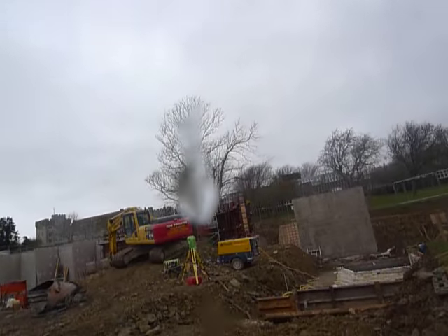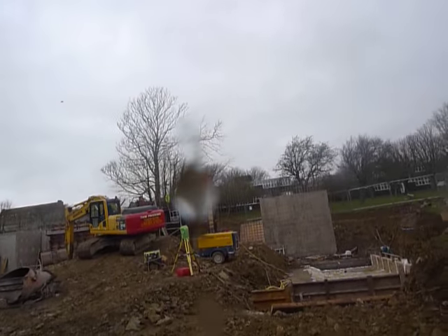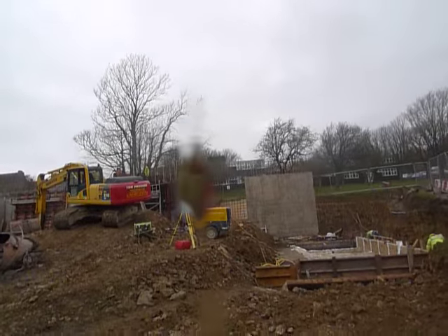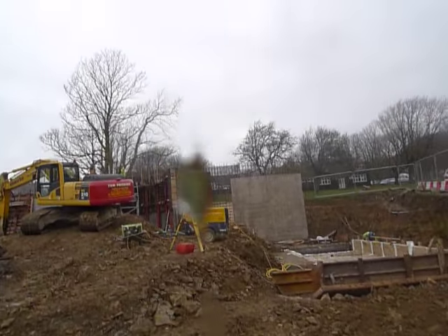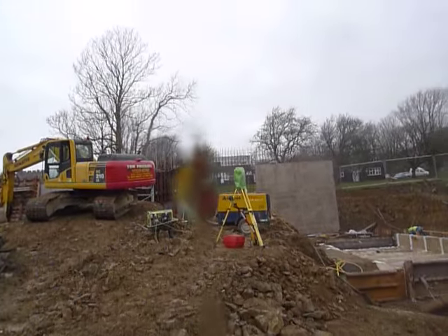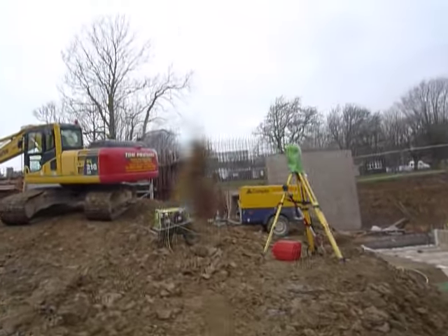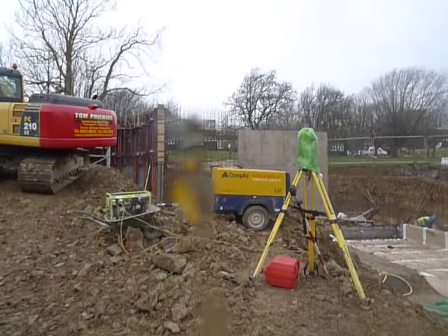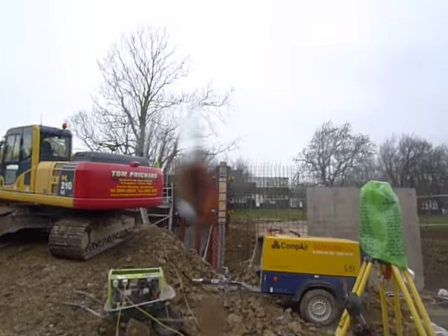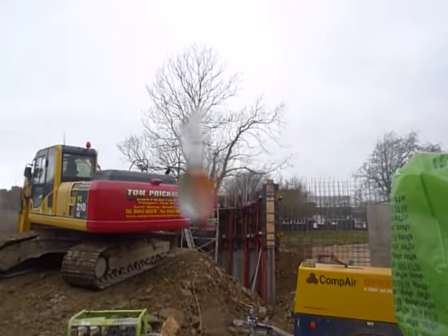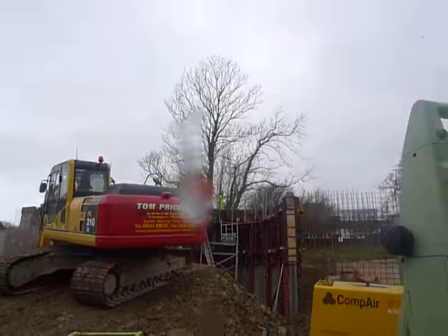So if you bear in mind the driver wants to go after about half an hour, and the recommended design is that we put in 1.5 meters cubed, wait an hour, and put in the extra 1.5 meters cubed. There's a clash of interests there, so we've got to try to hit a happy ground. And we made a slight delay, but nothing like what was textbook.